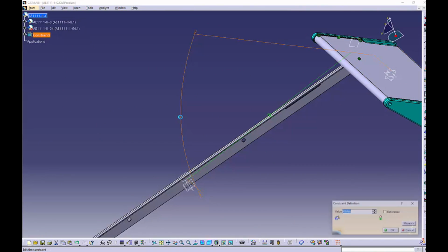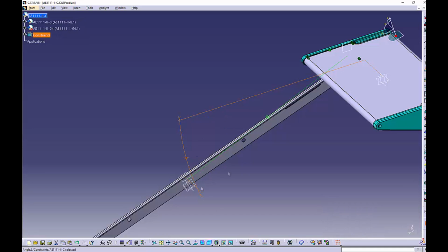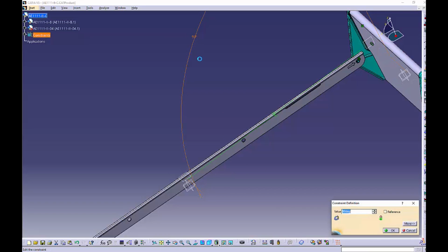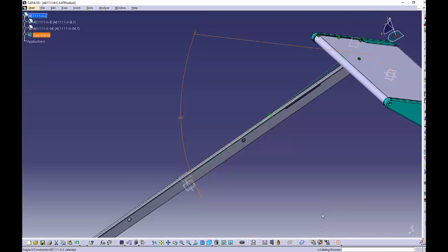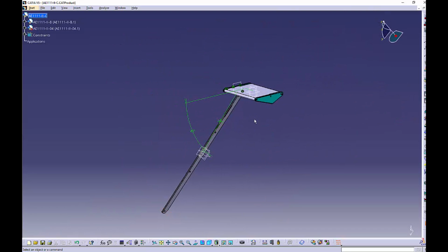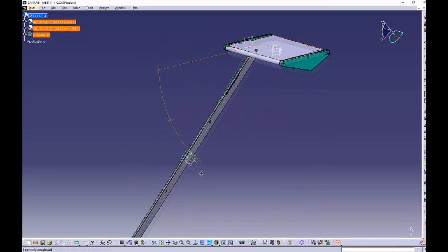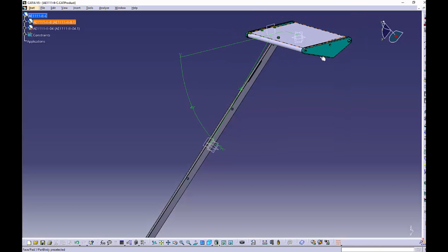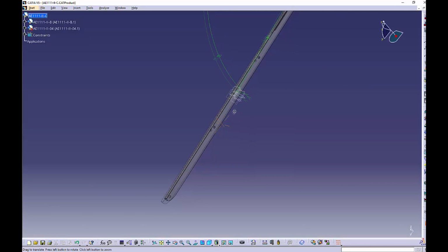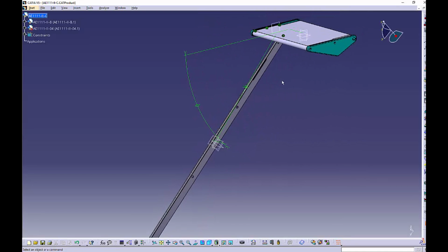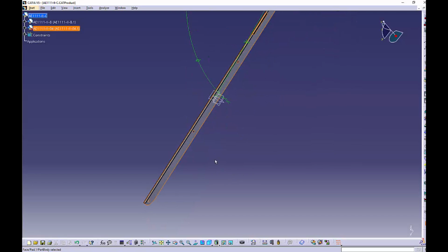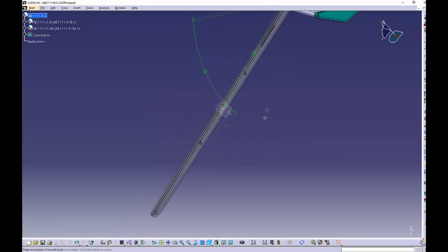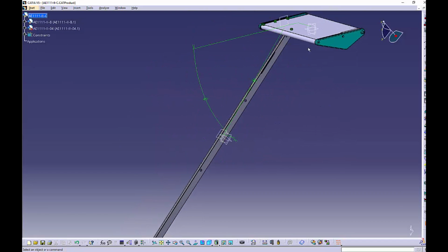Now we can change it every time without using the compass, like 20 degrees or 90 degrees. Yeah, but let's go back to 45. Update. Okay, but now we just have one stair up. Our stairs doesn't just have one stair, we need 3 more. So how can we make it? Well, we can copy and paste it and then constrain it again 3 times, but this is a waste of time, we can make it much quicker, because for making the stairs frame, we used the rectangle pattern tool. And with this rectangle pattern, we can also copy and paste our stairs to these holes.